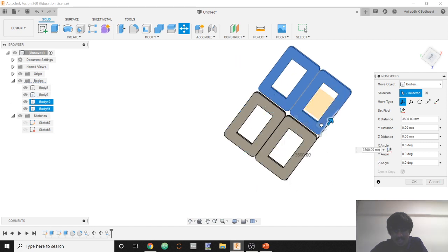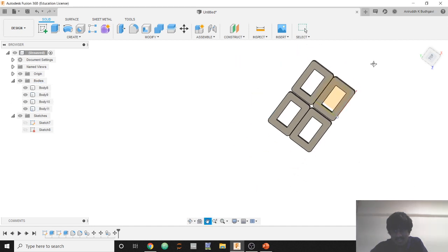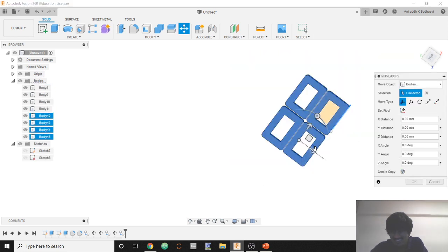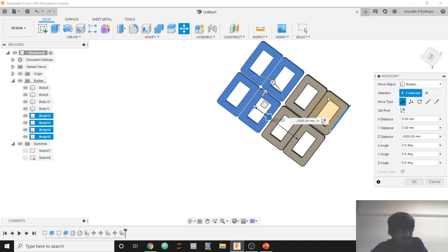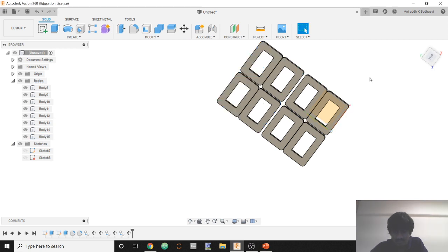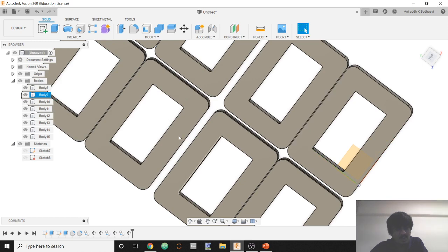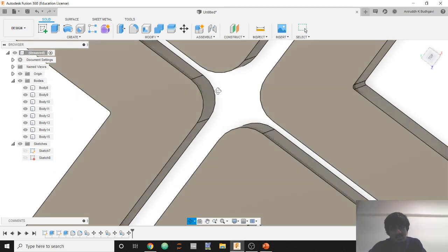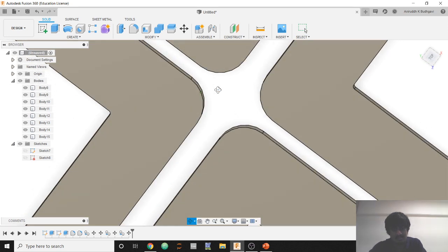Let's say I want to have these in a grid like this. Okay, so if you want to have these like this, and let's say I want to have them sticking to each other, so oftentimes what will happen is at these corners there will be sometimes a lack of space because of a 1 mm odd or say half mm error. So that error would be introduced during the 3D printing process.